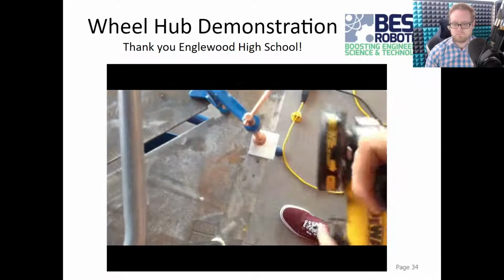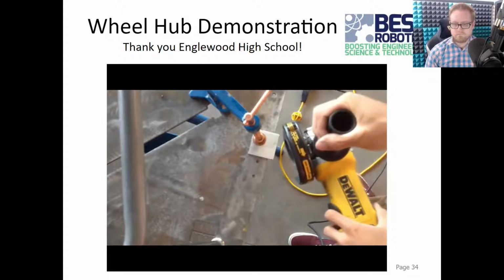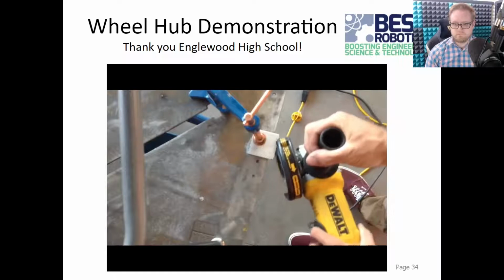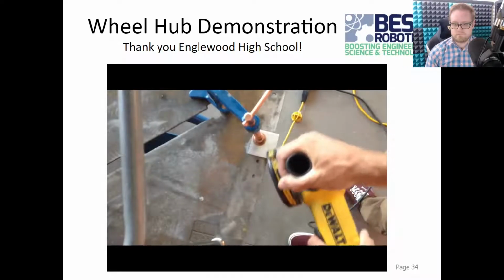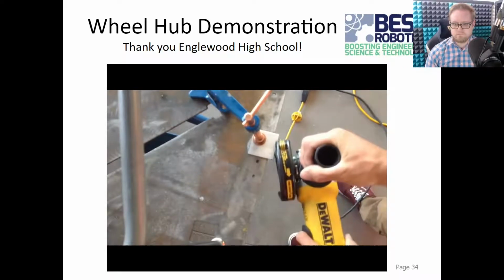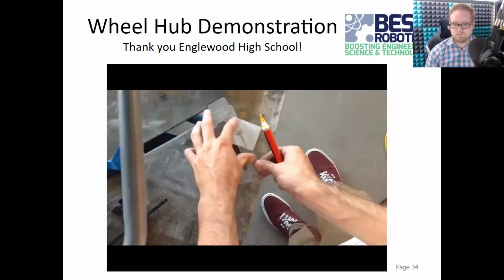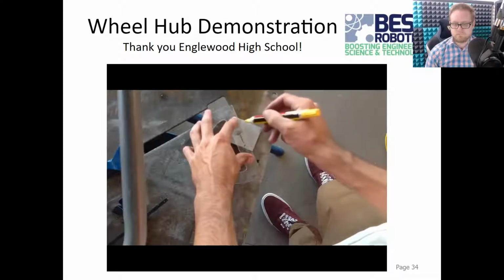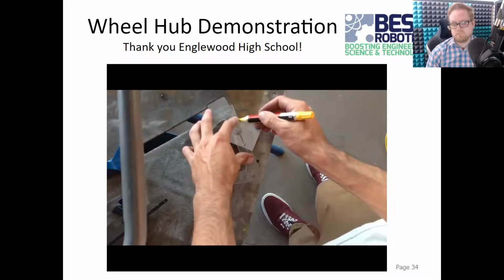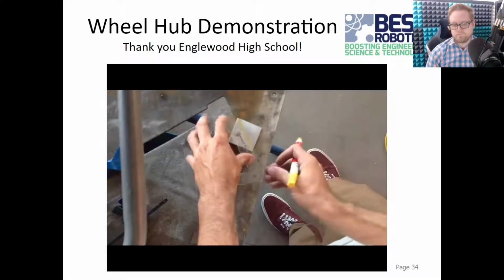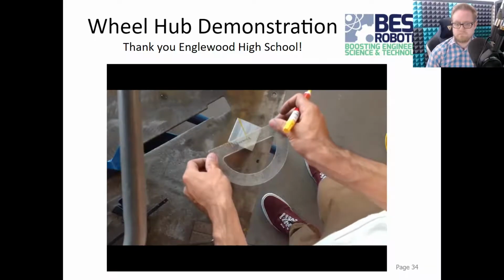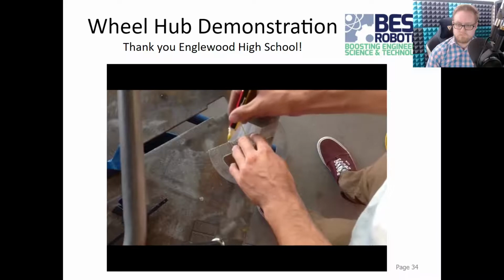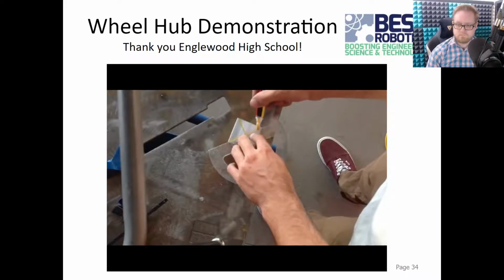Now you use a different attachment on the grinder to smooth the edges. Now to put a hole in the center of the block, you're going to take a straight edge and draw an X. Simply put the straight edge corner to corner and draw a line. The center is going to be the most middle of the block. This is where you want to drill a hole.